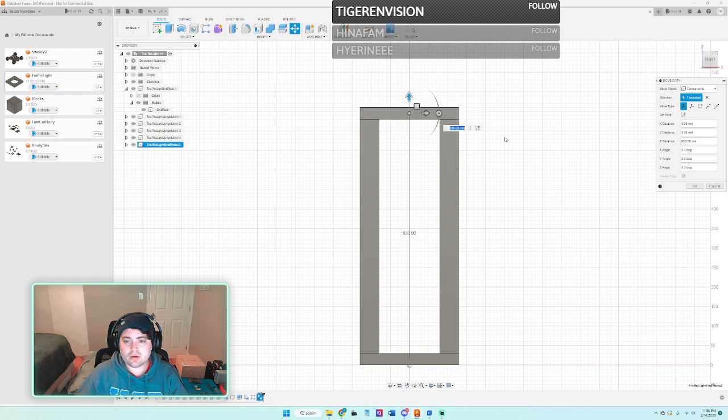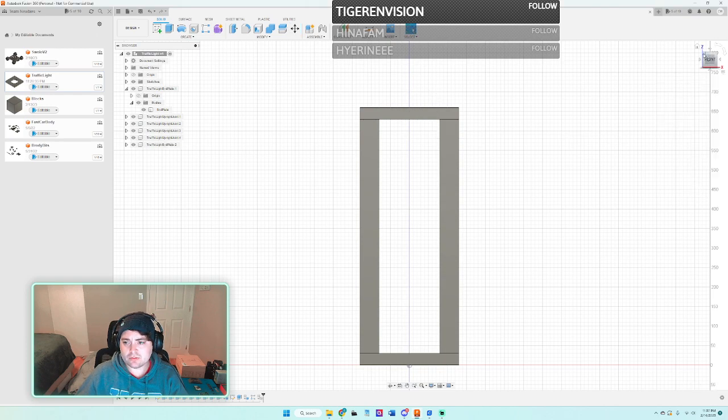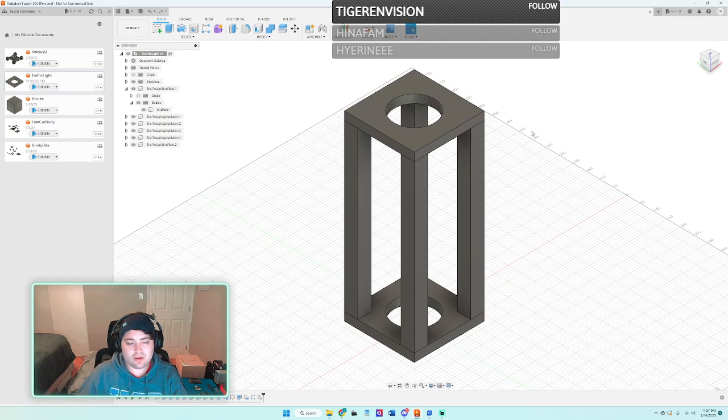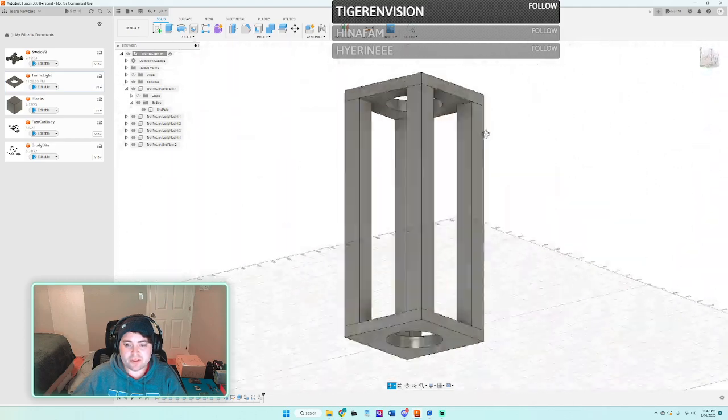And we'll just set it right on top, just like that. We're displacing it by 630 because the lower plates are 30, and then the struts obviously are 600, which means we have to displace by 630. Alright, so this is the initial template of our traffic light here.